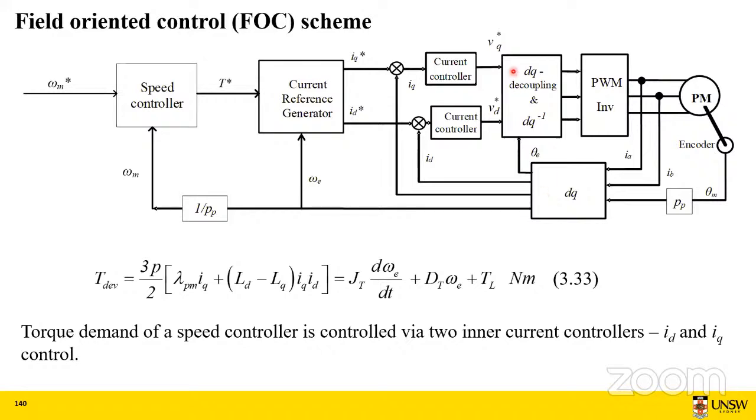If you remember, cos theta minus 120 degrees. What is that theta? In fact, that is the electrical rotor position of your rotor. If we have a sensor that can give us the mechanical rotor position, multiplying it by pole pairs, we will get the electrical position theta, and we can use this for our Park's transformation.